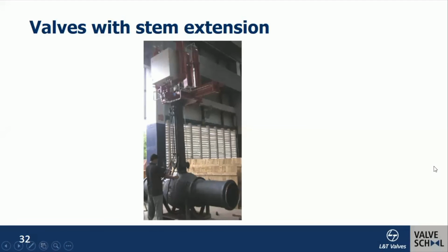the stem and the actuator operator will be available at a convenient level from the ground level. So typically the distance up to this would be buried under the ground, and the person standing on the ground level could access the actuators and other related components. Also, the auxiliary lines like the drain, vent, seat sealant lines and the stem sealant lines are brought to the top at a convenient level for easy accessibility above the ground.